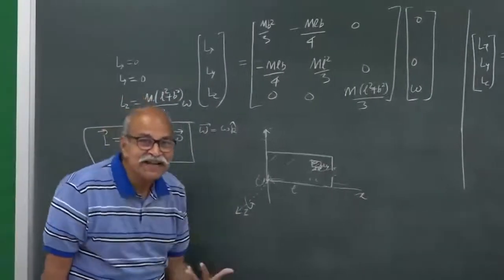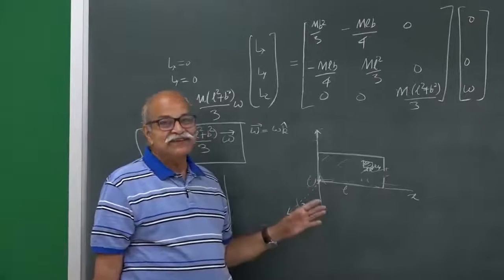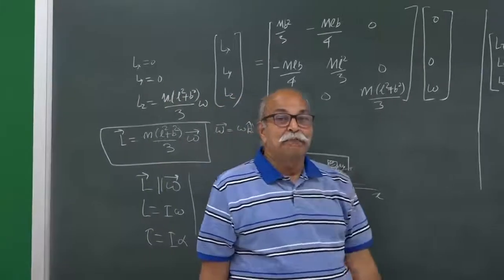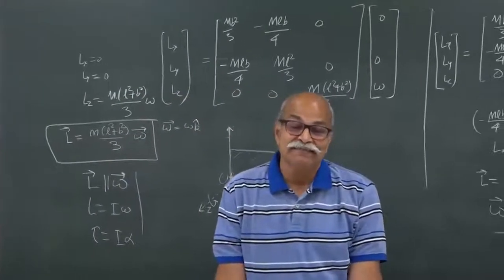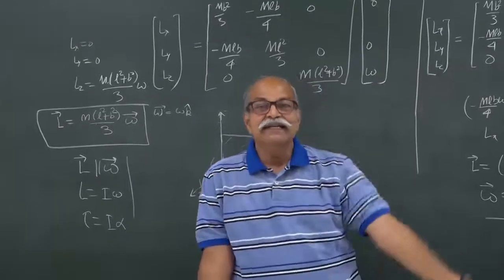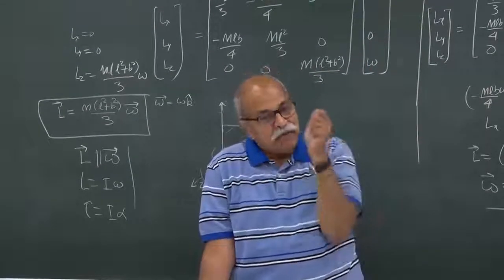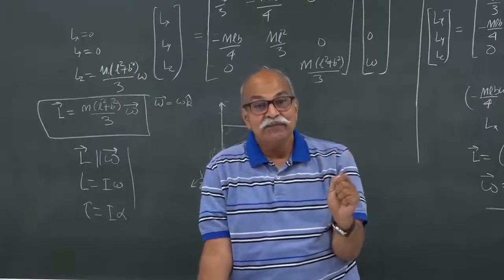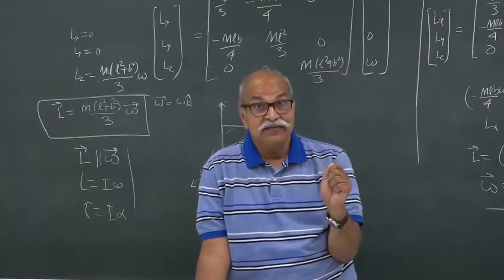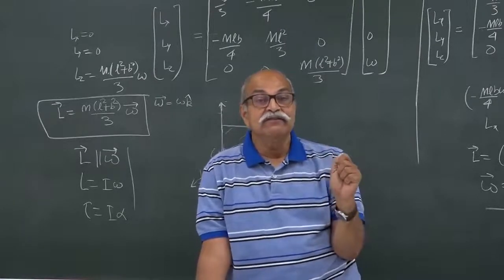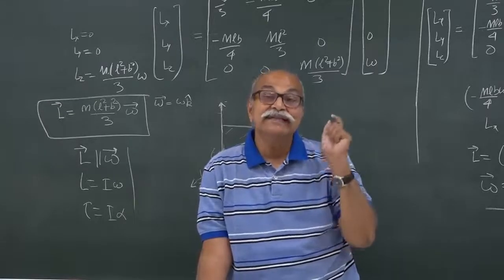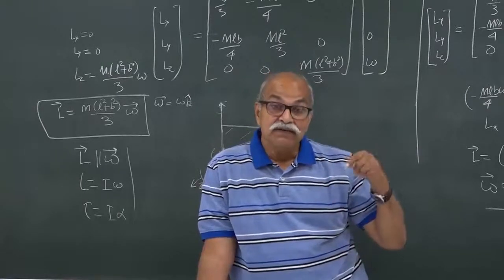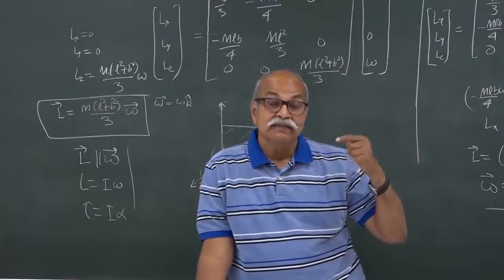So, what is so special about this z axis which is not there in the y axis? And there comes the concept of principal axis of the system. If you have any rigid body and you are given a point fixed in that rigid body, from that point you can definitely find at least one set of 3 perpendicular directions in which the product of inertia terms are 0.